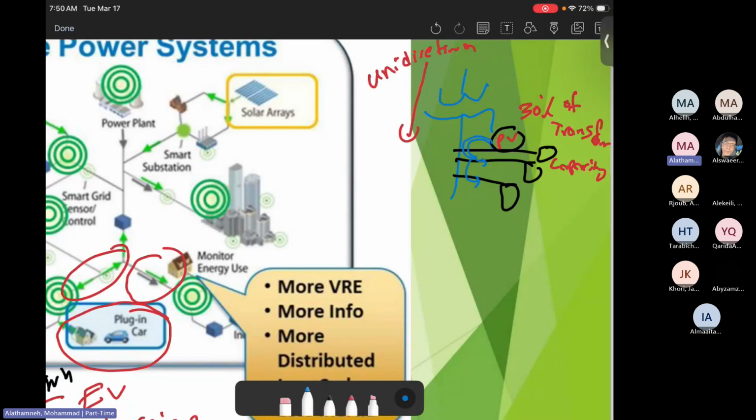That's what's happening in real life. So the renewable energy sources connected in low voltage will only be within the low voltage range. They will not go to the medium voltage. You will not see the distribution transformer act as a step-up transformer, converting low to medium. No way. All of the distribution transformers that we have here are just step-down, which is basically unidirectional. That's a challenge. That's why the current protocols say it will not exceed 30%.